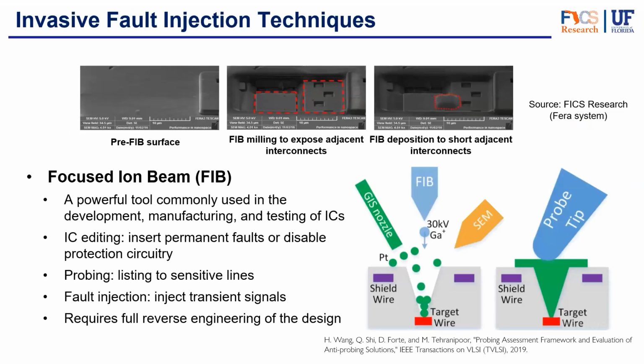And the last one, the invasive fault injection attacks, are based on focused ion beams, or FIB. FIB is used in manufacturing facilities for last edits, based on tracing some paths, adding or removing some circuits or layers, and making some patches at the last level to address manufacturing defects.